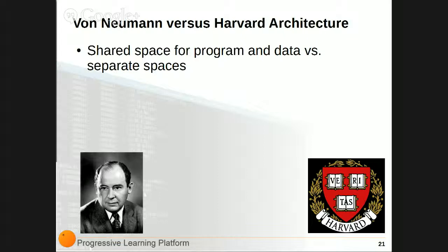You don't have that problem with the Harvard architecture. Well, what are the cons for Harvard architecture? Complexity. Now you need two sets of buses for both program and data. But more buses mean more wires. Let's talk about a 64-bit CPU. Now you go from 64 wires to 100 wires. That's a lot of real estate on your silicon, right? Does that make sense?